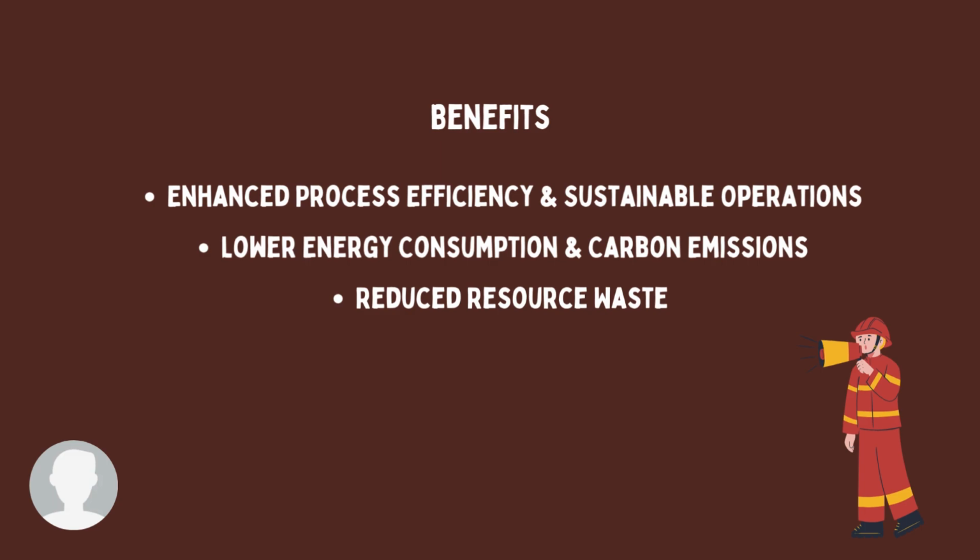Lastly, reduce resource waste. Uncontrolled pressure surge can cause leaks, pipe bursts, and material loss, leading to wasted water, fuel, and raw material. PRVs and surge protection devices optimize flow control, reducing unnecessary loss.